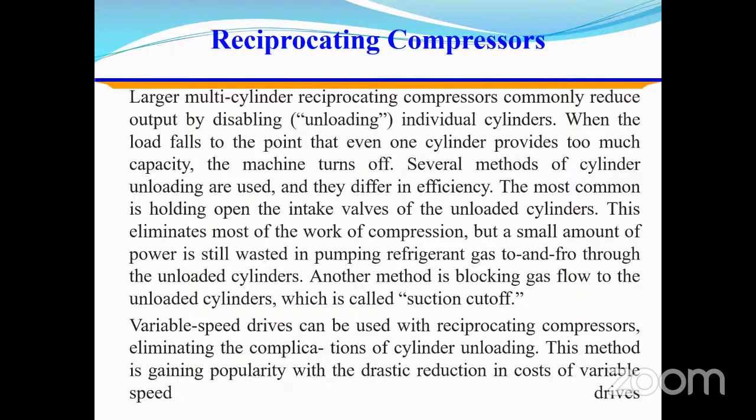The most common is holding open the intake valves of the unloaded cylinders. This eliminates most of the work of compression, but a small amount of power is still wasted in pumping refrigerant gas to and fro through the unloaded cylinders.